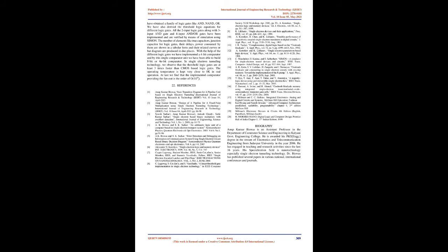Conclusion. We discussed a novel design of threshold logic gates implemented in single electron transistor technology, where the basic operating principle is the single electron transport phenomenon. A generic linear threshold logic gate implementation is elaborately discussed, from which we have obtained a family of logic gates like NAND, OR. We have also derived the threshold logic equations for different logic gates.